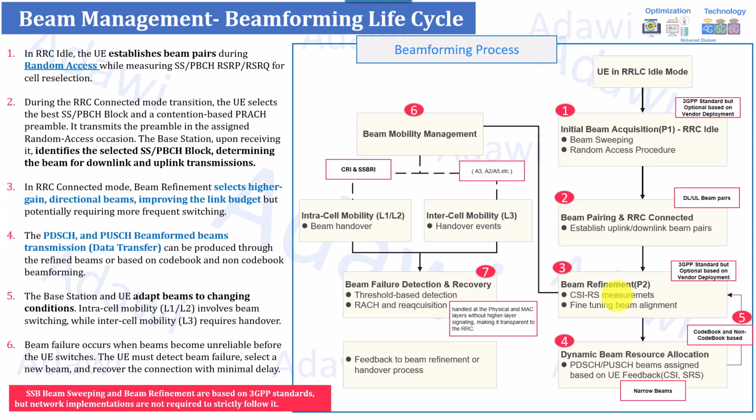So once the beam refinement is done, which is the CSI-RS beam format, the user will start measuring the CSI-RS and reporting some information to the network, to allow the network to allocate the best beam or the traffic beam, which is the PDSCH, or physical downlink shared channel, or if you're speaking about the uplink direction, the physical uplink shared channel. This can be done through different methods, even based on the CSI-RS, which is the channel state information reference signal measurement. We'll be covering this part in detail, which is called codebooks in the downlink direction, or the sounding reference signal. So this feedback will be reported to the gNB. The gNB will decide, based on this report, what is the best beam to be allocated as a direction to the user, and it will give a narrower beam. We will also show this in detail, once the feedback is sent and so on.